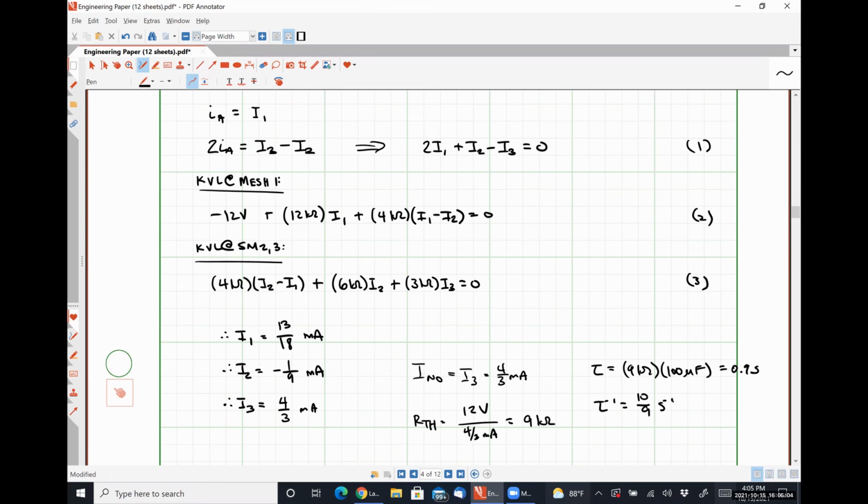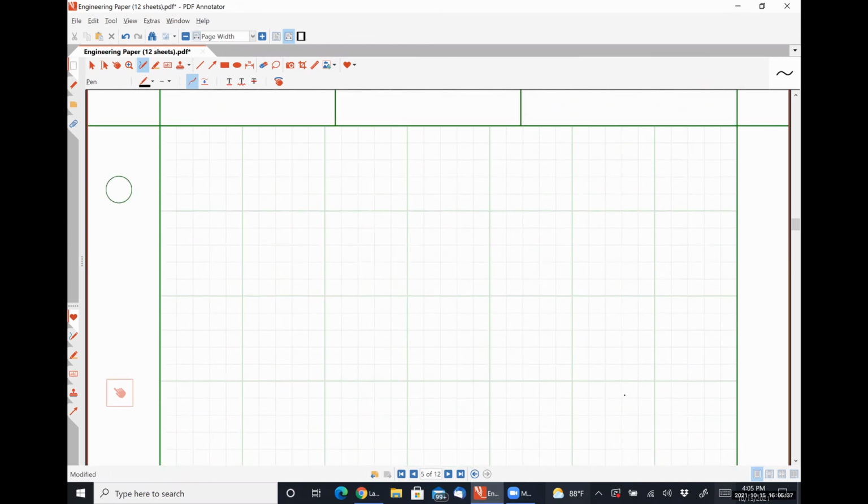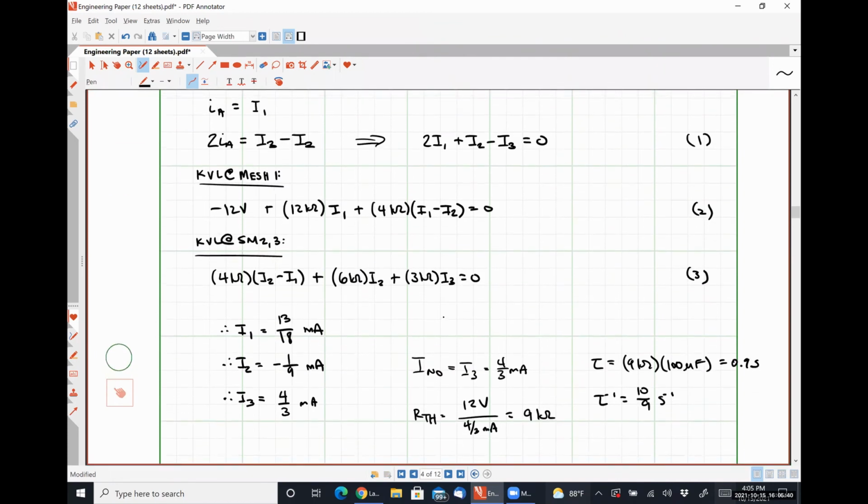Skylar, how can I help you? Seconds. So a time constant is a measure of time. It's how long it takes for the signal to decay. So the unit should be seconds. We just figured out how long that takes. So if 1 tau is 0.9 seconds, it would take roughly 4.5 seconds-ish for that capacitor to fully charge or discharge, because 5 tau is infinity for engineers. So, all right. Sorry, Joy. We good?